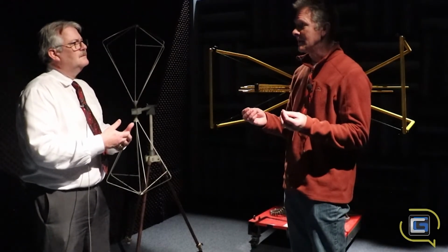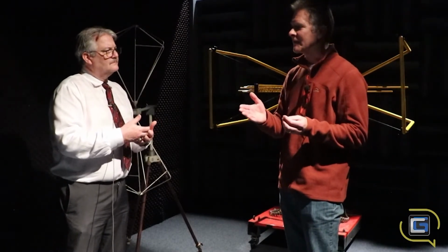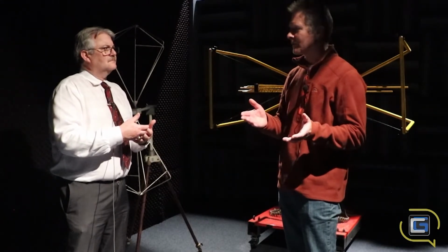One thing that you run into in power supply design or using COTS power supplies is that most of the supplies that we use are designed and tested to FCC requirements. FCC typically only cares about going down to about 150 kilohertz. We test to MIL-461, which takes us all the way down to 10 kilohertz.